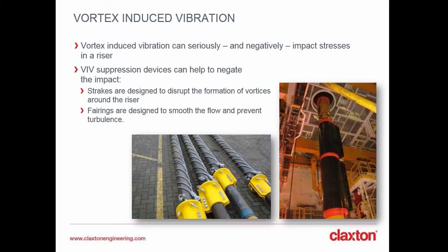When the vortex shedding frequency approaches the natural frequency of a marine riser, the cylinder takes control of the shedding process, causing the vortices to be shed at a frequency close to its natural frequency. It's all a little bit complicated, but this phenomenon is what they call vortex shedding lock-in, or synchronization.